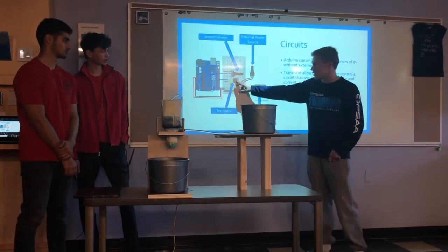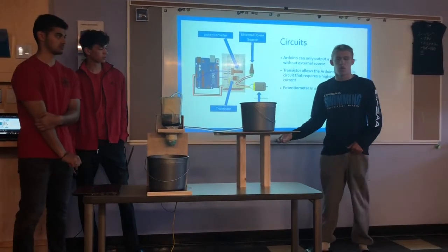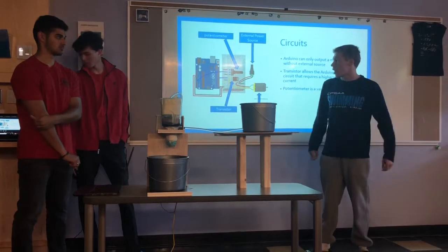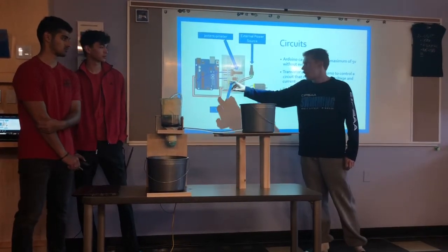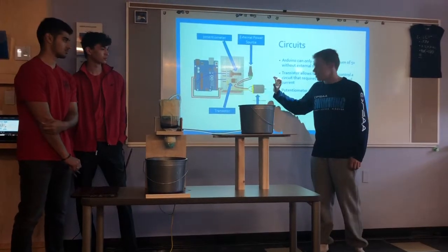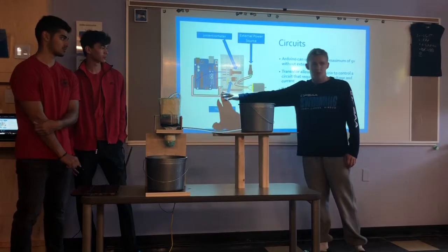Secondly, we added a transistor to our circuit. As I said before, the Arduino can only output 5 volts. This transistor allows the Arduino to control circuits that have a higher amount of current and voltage than the Arduino's maximum output.